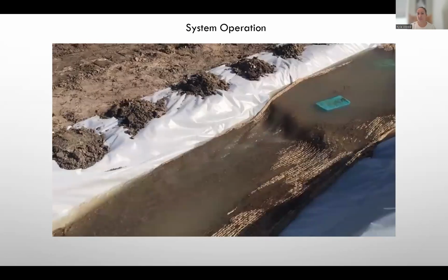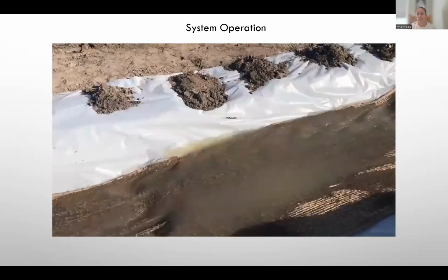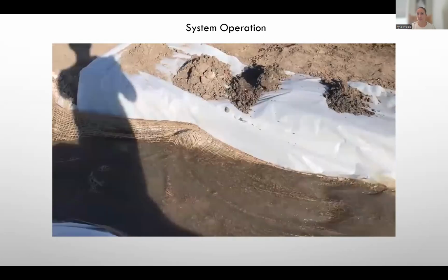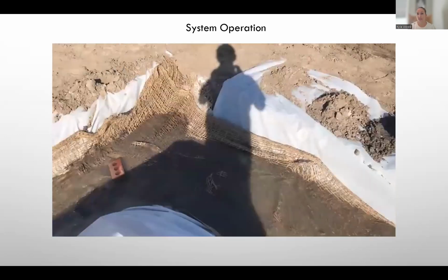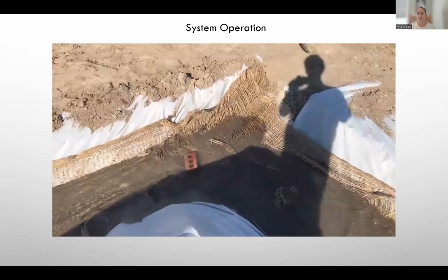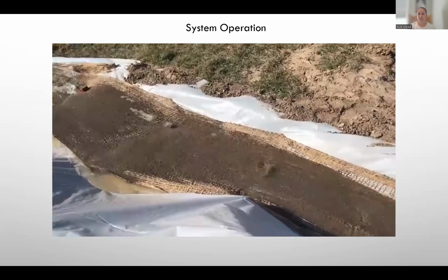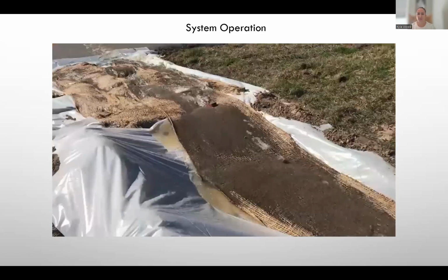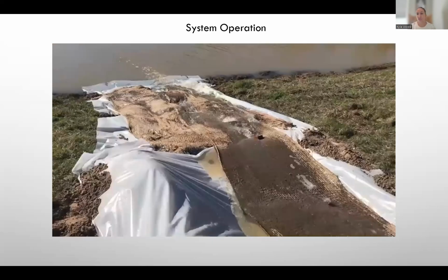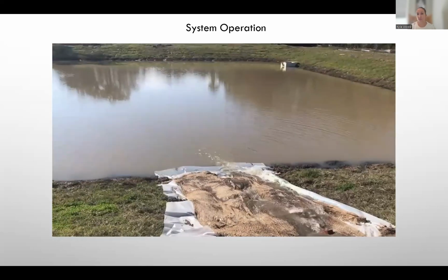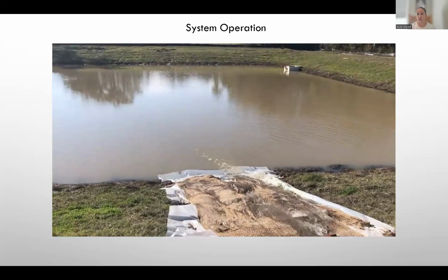you would have to manage and clean out that basin to whatever your design standard was. I think it's usually at 50% capacity that you have to clean out a sediment basin. Don't quote me on that. Basins aren't my specialty, but I'm pretty sure. So basically you would just maintain it the same. There's no special disposal considerations for anionic PAM.